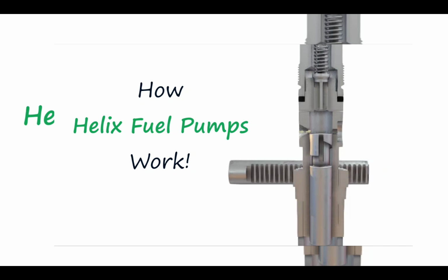Okay? So you injected more fuel. This is called the effective stroke of the plunger. So each plunger has an actual stroke, which is the movement from the bottom dead center to the top dead center based on the cam's profile. Okay? And the effective stroke, which depends on the rotation of the helix of the plunger and how long it closes the return port.